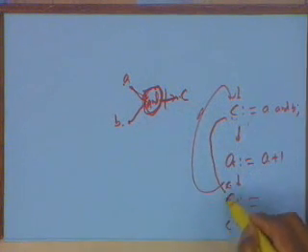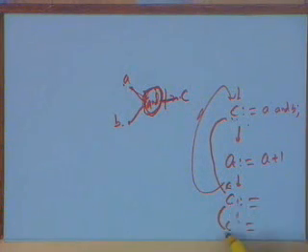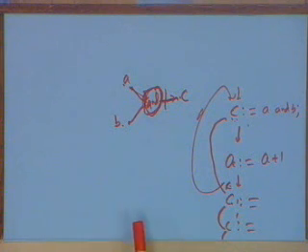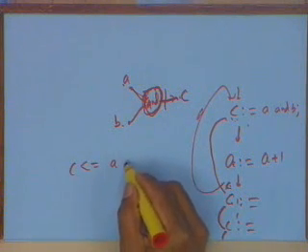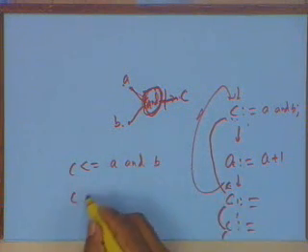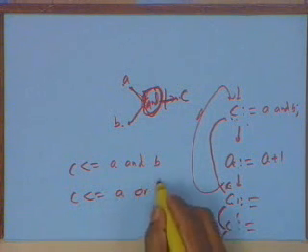In the range from this to this, this value will be used; in the range following this, the last value. Whatever the last statement you executed, that's the value being used. But in VHDL you cannot do that. You cannot write another statement, C is assigned A and B, and then say C is assigned A or B. It's meaningless.